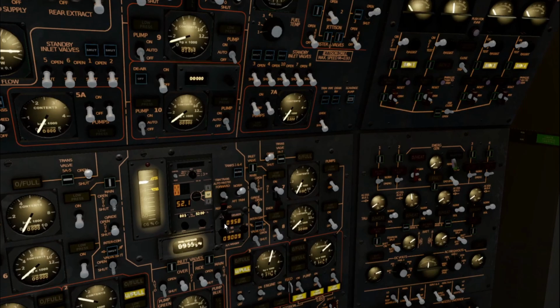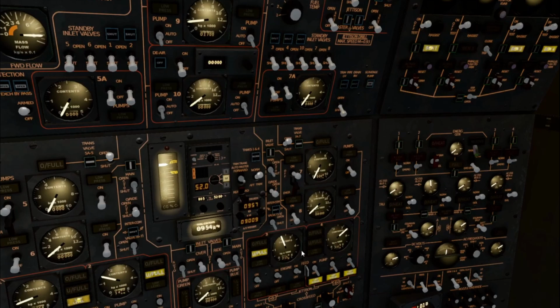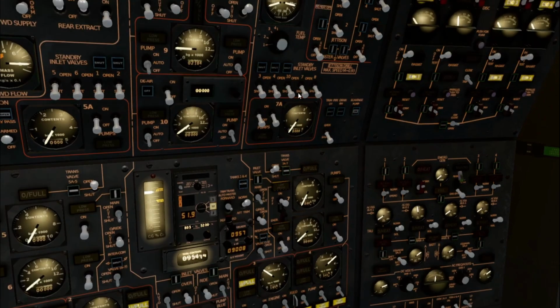If you want to know more about fuel transfers, I highly recommend checking another video tutorial, that second part, which is 1 hour for this purpose. But the main basics are keep these more than 1 ton and I'll be good. Rearward trim, CG in the back. Yes, we have it. Stop it.